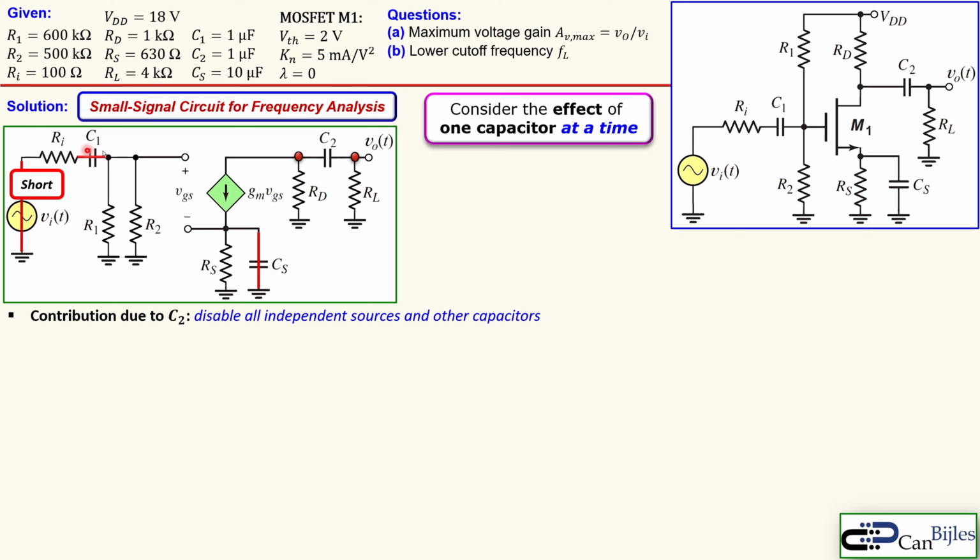And if I now do again the voltage divider rule, that means that this voltage node here is also 0. That means I measure here between these two nodes 0 volts. That means VGS is 0 volts, meaning gm times 0, meaning this is a current of 0 amps. That means this is an open circuit. So that means actually affected the following.